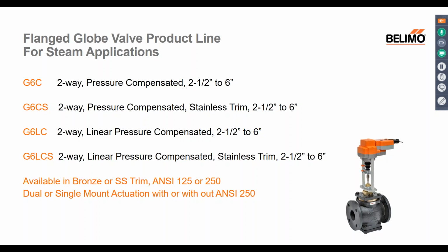Linear or equal percent. Some things you read might tell you linear for steam control, but on low pressure steam, a lot of people, including me, like equal percent because our loads vary so much with low pressure that equal percent will give us better control at the low end. So we've had great success over the years using equal percent valves for low pressure and below 15.